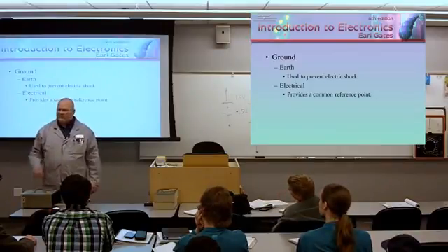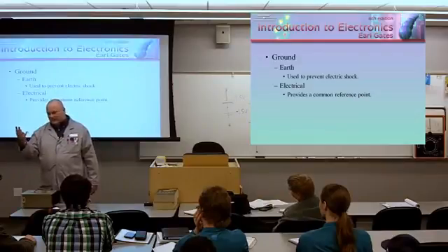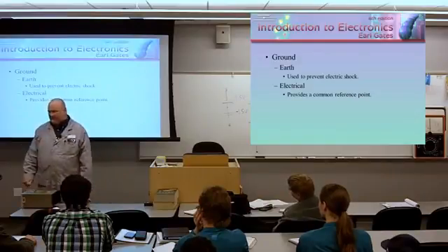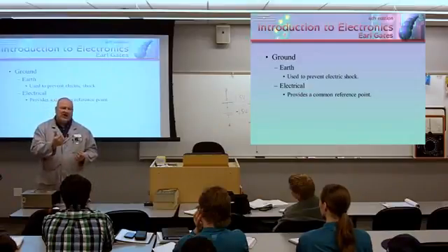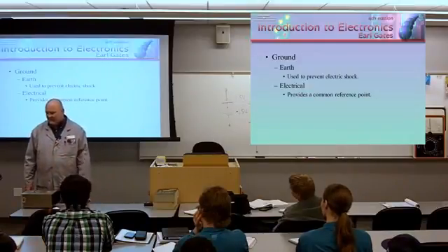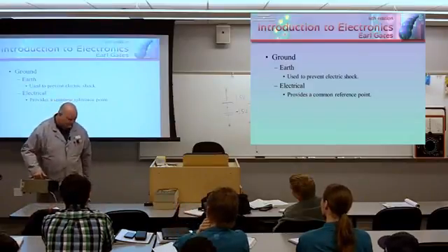Generally, yes. Some of the worst shocking experiences I've ever had were working on a lot of tube circuits, because those tube circuits were notorious for being two-prong, old school tube amplifiers. You plug it in two-prong, and you didn't have that electrical ground in there. All of a sudden, you go up against the chassis, and you're getting zapped by 300 volts. Make sense?